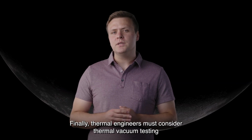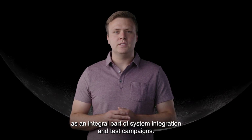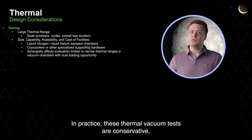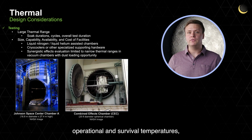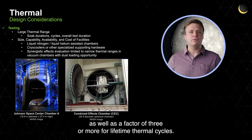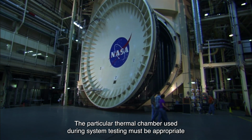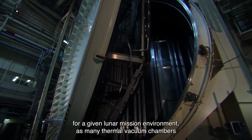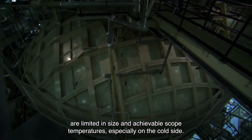Finally, thermal engineers must consider thermal vacuum testing as an integral part of system integration and test campaigns. In practice, these thermal vacuum tests are conservative, applying margins to both hot and cold operational and survival temperatures, as well as a factor of 3 or more for lifetime thermal cycles. The particular thermal chamber used during system testing must be appropriate for a given lunar mission environment, as many thermal vacuum chambers are limited in size and achievable soak temperatures, especially on the cold side.